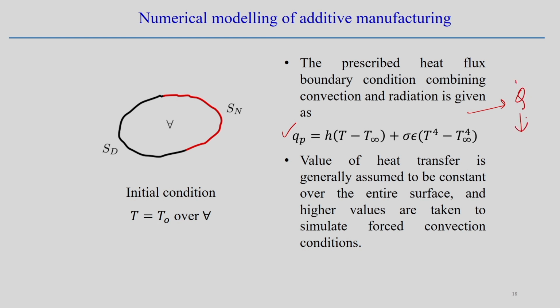So, that passes through, or maybe is incorporated through the governing equation, but over the boundary this is the heat loss by convection, this is heat loss by radiation. So, what will be the heat loss by convection and radiation? That is with the heat conducted to the domain of the boundary. Whatever heat is conducted to the domain, basically at this point the heat flux through the mode of conduction, is equivalent to the heat loss by the radiation and convection. In that way we mathematically represent the boundary interaction.